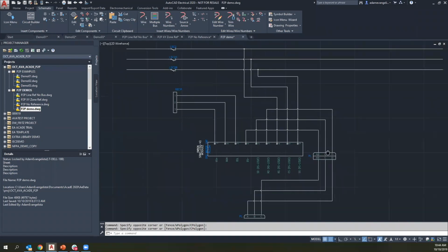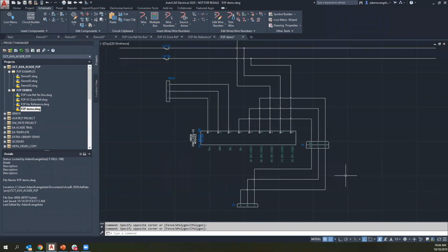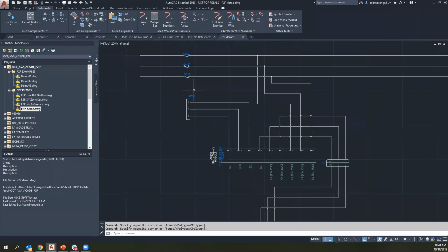Honestly, one thing about AutoCAD electrical wires is that they just kind of represent regular AutoCAD sketches. And when I was preparing for this particular presentation, a lot of my time was just deleting and redrawing the multi-bus, since it's so easy to redraw these. So that's one option, just delete them and draw them again, which isn't the best option for sure.